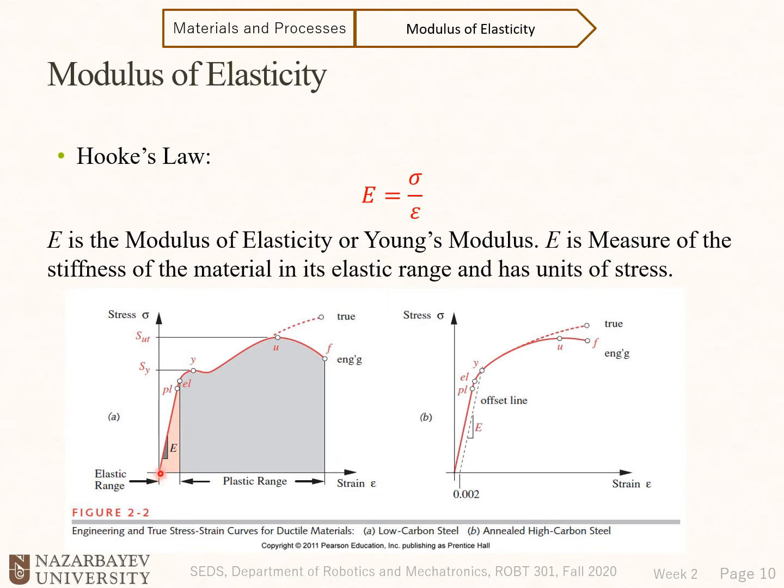The length of the specimen increases. And if we release the force before we reach the PL and EL point, the material will spring back to the initial length. So the material will act as just a normal spring.